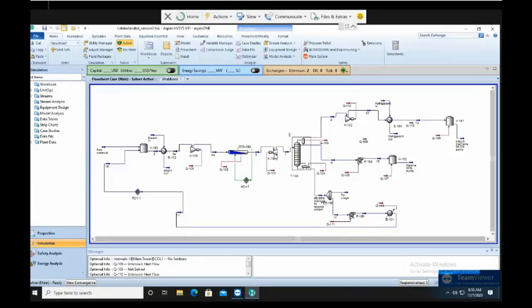I have tried to repeat this, but it is difficult. You have to be patient and do it step by step because it does iteration. When the iteration has gone far off, it cannot go back to the actual one. If you're lucky, you get this. So the keyword here is patience. You have to try many times, and I deleted it many times. For the DC, I think the first step I did was choose a total condenser first, where both methane and ketene would be in one stream, and once it converged, I changed to a partial condenser,